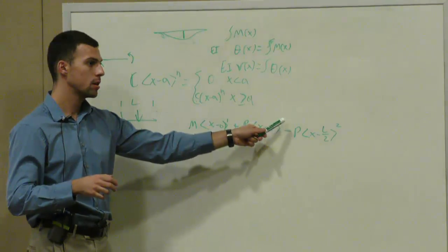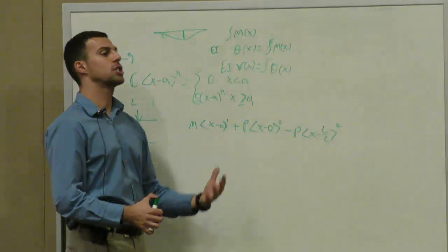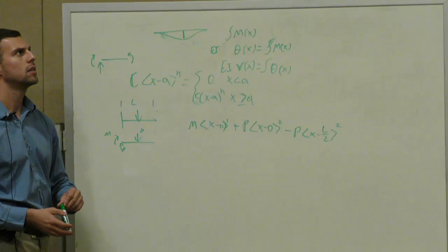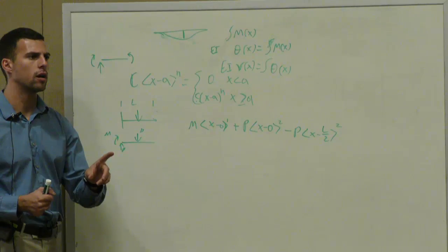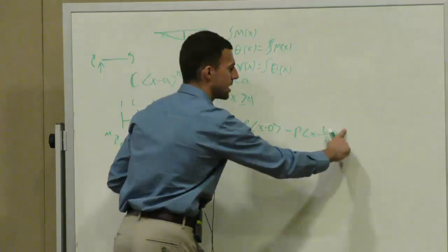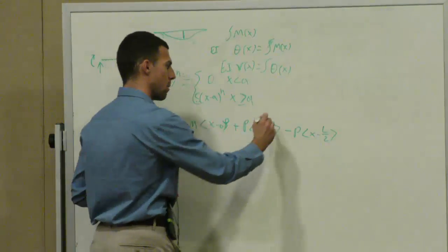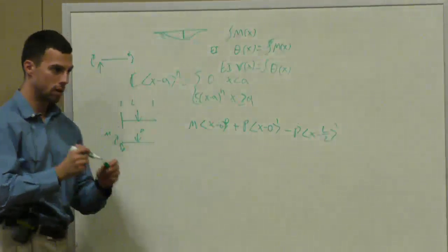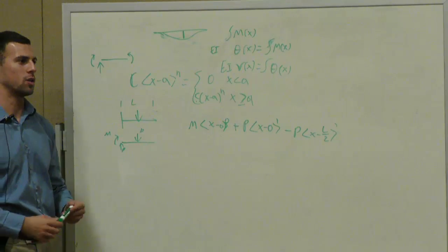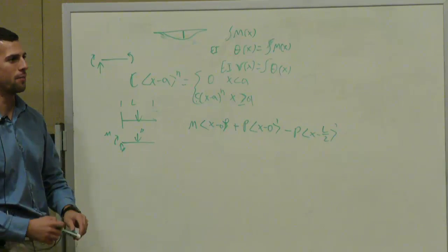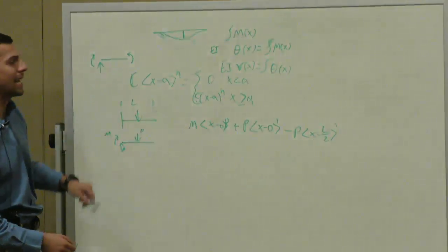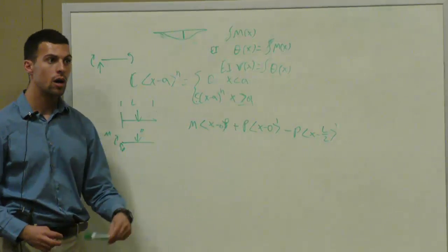This too? That is simply because of the type of load, right? So actually, no, I'm sorry, I think I'm wrong. Moments are to the 0 power. Point loads are to the first power. Sorry. Yeah. If that was your question, because in the book it is a 1, the book is right. I was dumb for a second. Yeah. Point loads are to the power of 1. Freestanding moments are to the power of 0.